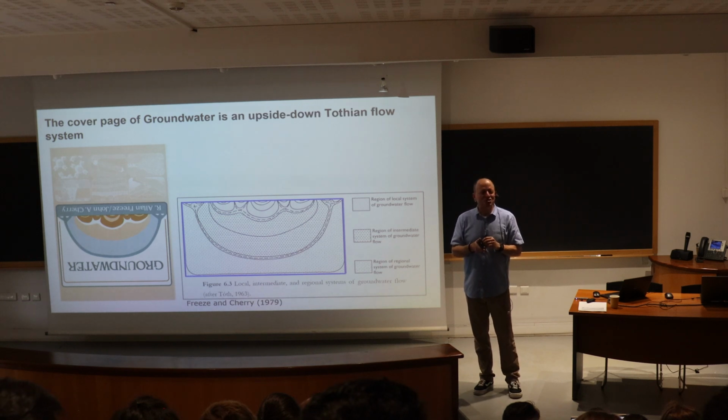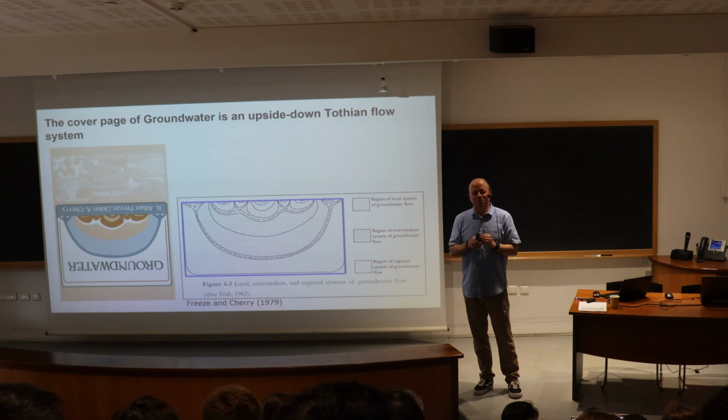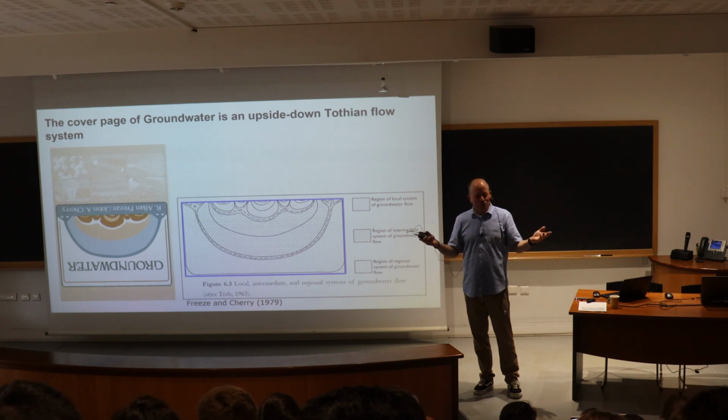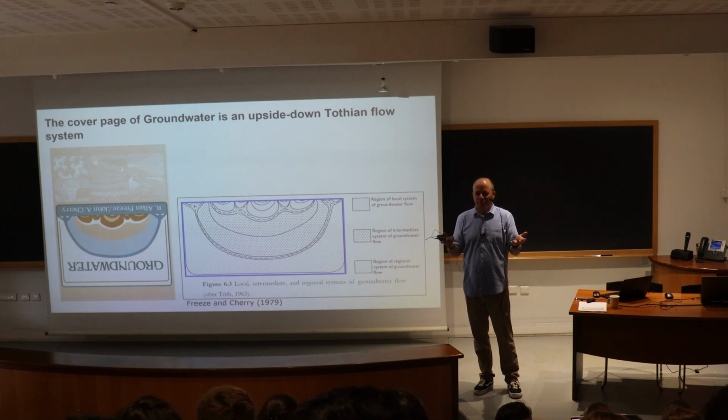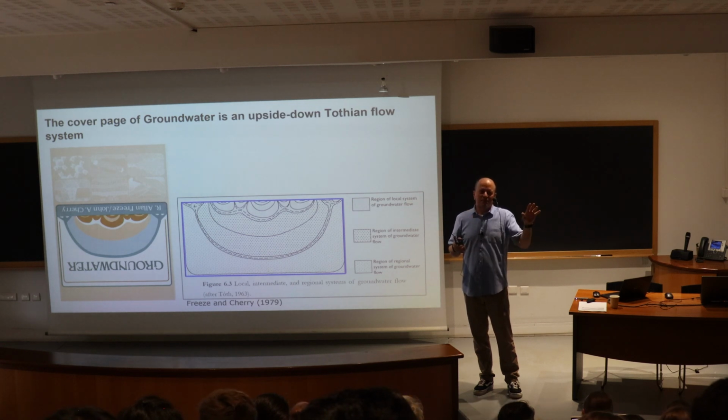Yeah, that's a very good question. You try to choose as much as possible natural boundary conditions, which would be contacts between low permeability and high permeability systems. So, like if you do 3D modeling, the base of your model probably will be some perhaps bedrock that is not very fractured. So okay, this will be impermeable. And then you have to, on the sides, decide, okay, this might be a water divide or another contact. And then at the surface, well, you have the surface network, drainage network that you will represent in some way.